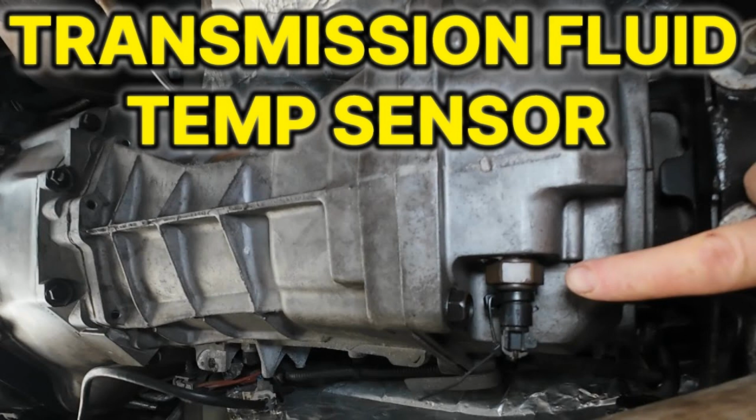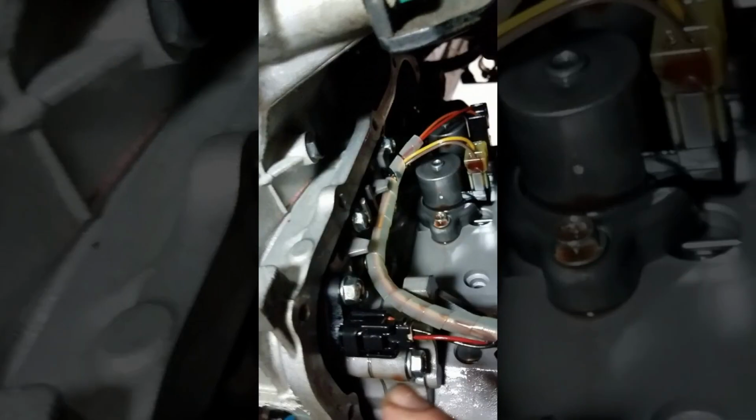3. Checking transmission fluid level. Check that the transmission fluid level is correct. If the level is too low, add transmission fluid in accordance with the manufacturer's specifications. Also check the transmission system for leaks and carry out any necessary repairs.